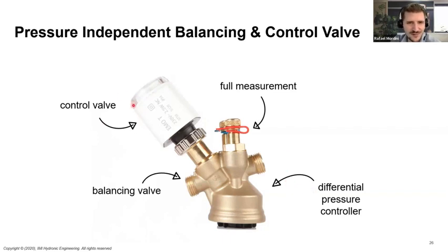How does it work? Well, it's a control valve, as you can tell by the actuator, and it has the hand wheel here. It's inside the actuator. You have to remove this module here to access the hand wheel. We have PT ports, so you can measure to do the balancing, and you see this belly part here. This here is what ensures good controllability on the control valve. Let's take a better look.